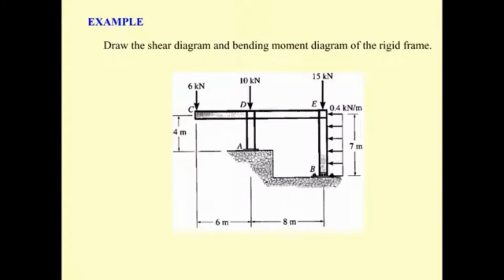If you recall the example that we had, with 2 pieces of beam and column, and we also had the frame with 2 columns and 1 beam, this one has 2 beams and 2 columns, and beam BC is going to be the cantilever beam, attached to the joint at D, and has the column A supporting the joint D, and the beam DE connected to the column BE with the rigid connection again.